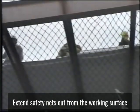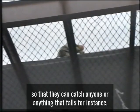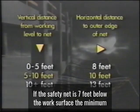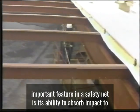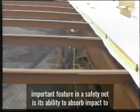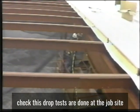Extend safety nets out from the working surface so that they can catch anyone or anything that falls. For instance, if the safety net is 7 feet below the work surface, the minimum distance from the outer edge must be 10 feet. The most important feature in a safety net is its ability to absorb impact. To check this, drop tests are done at the job site.